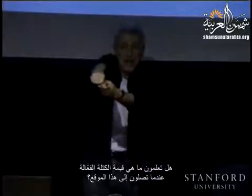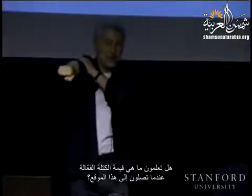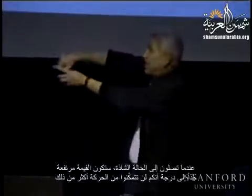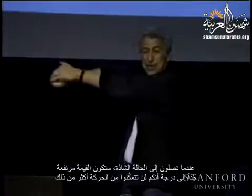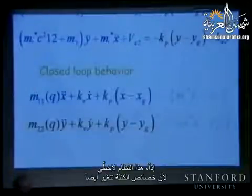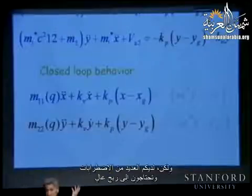And when you reach this location, do you know what your effective mass is in this direction? Infinite, yeah. Basically, when you reach the singularity, this will become so high that you cannot move anymore. It will become infinite. So this is a nonlinear system because the mass properties are also changing. Still, it's asymptotically stable. It works. But you have a lot of disturbances.